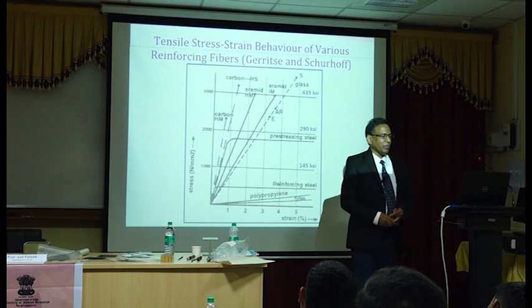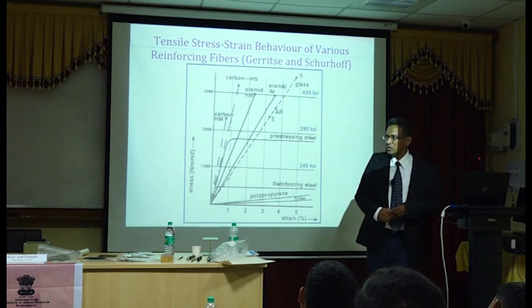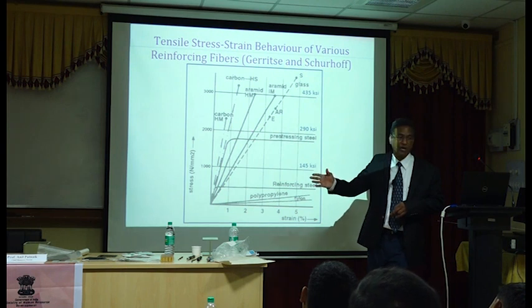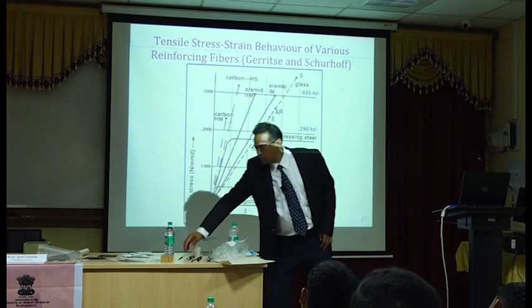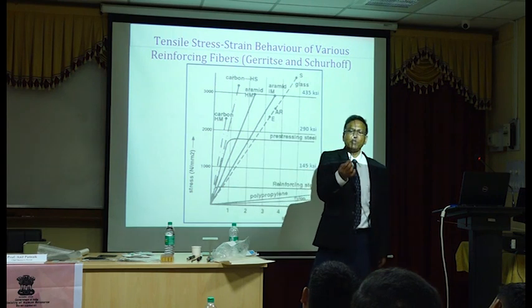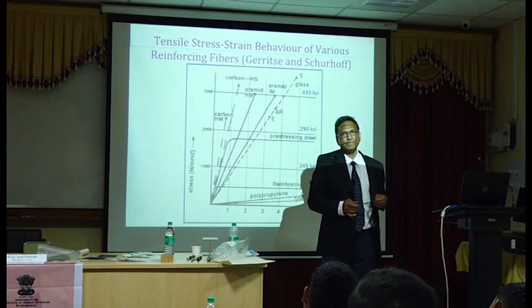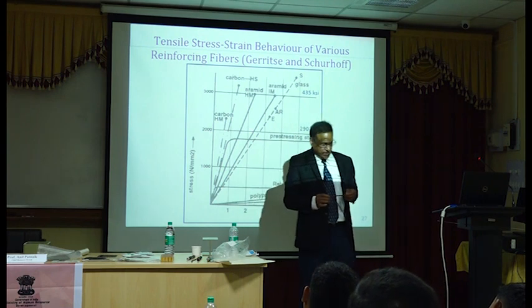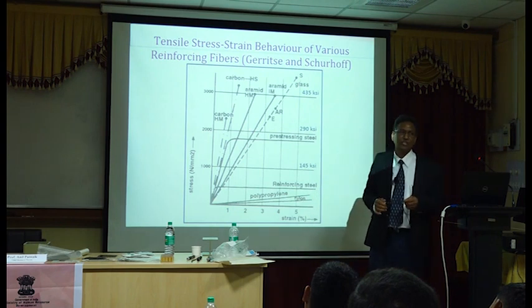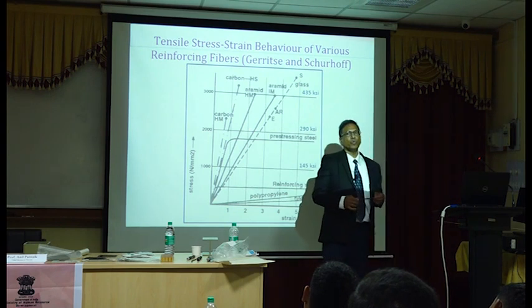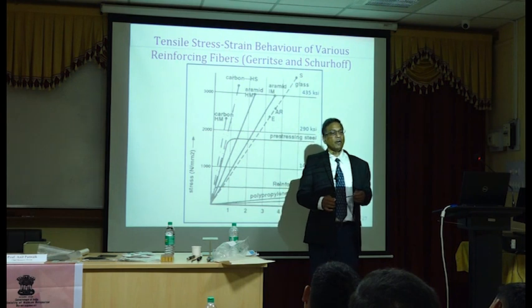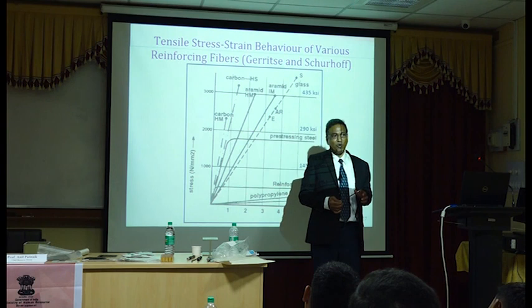So in my work, we found that the stiffness of the bars, at least with the matrix, with about 55% volume fraction, is like 6,000 KSI. 6,000 KSI is like 6 times 7, 42. So 42,000 or 42 GPa. 42 GPa stiffness, very low.